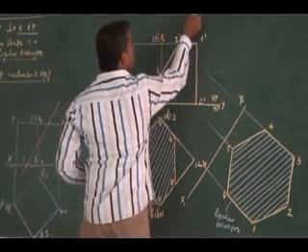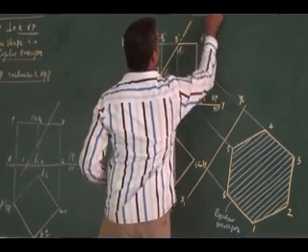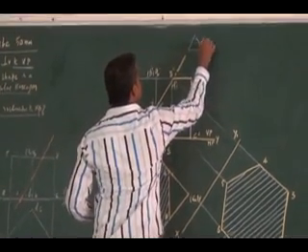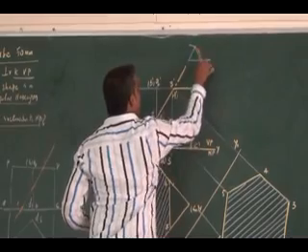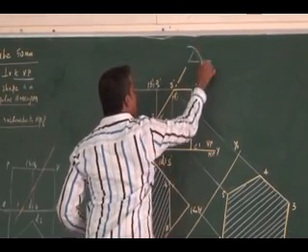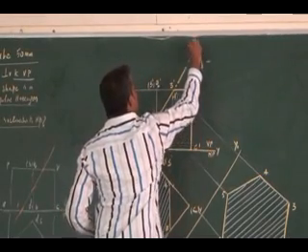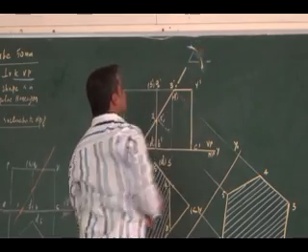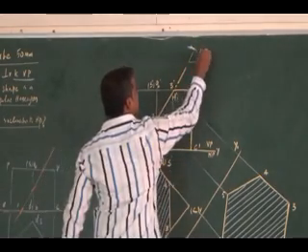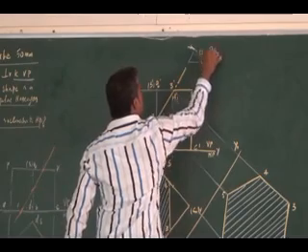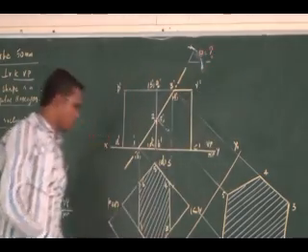Then finally, once you have drawn the true shape, then you find the angle, as it is asked in your problem. So you find the angle of this. Find the angle of this cutting plane with respect to HP, that is theta. You find it out and rotate it.